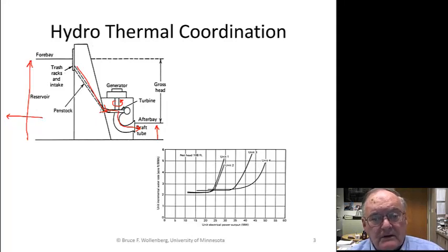But they are taking on a huge amount of water coming down this so-called penstock. That's the path the water takes. Up here, at the intake there may be a valve, and there are, we call them trash racks, just something to filter out sticks and twigs and leaves and junk that may get in here. That actually, the trash racks have to be cleaned periodically to keep the water flow coming into the turbine. If the forebay gets too low, if the level of the water is down here someplace like this, well, you can't generate anymore. So, and as the forebay level comes down, the water falls through less and less distance. You get a little bit of less output.